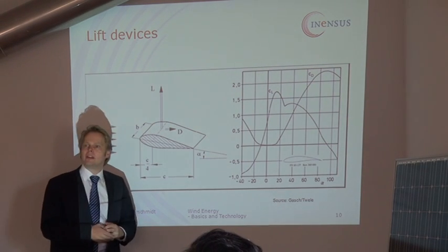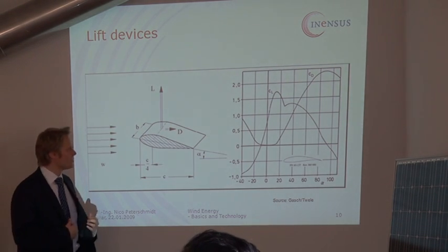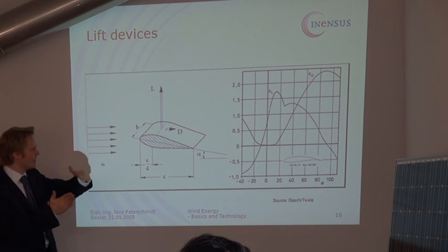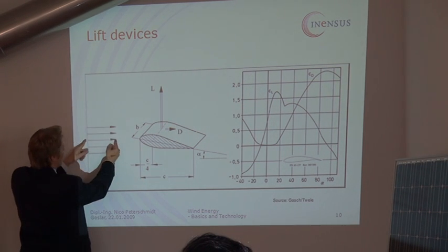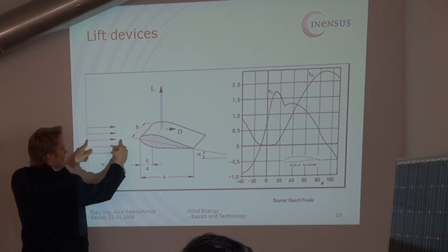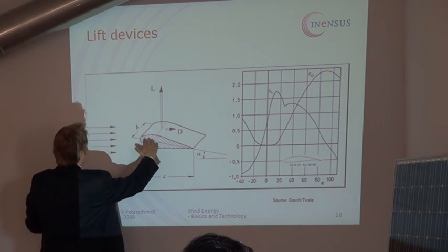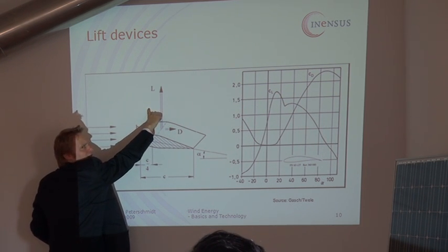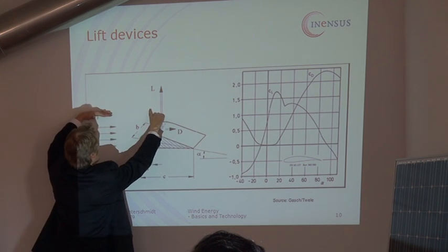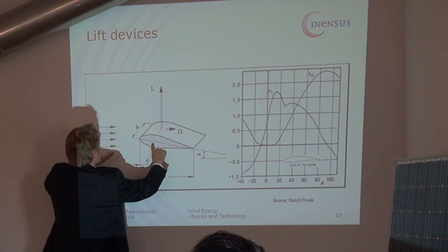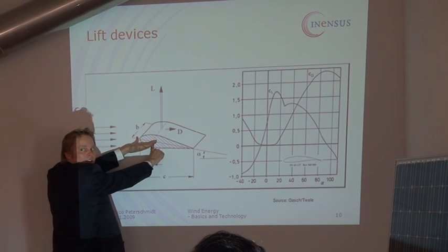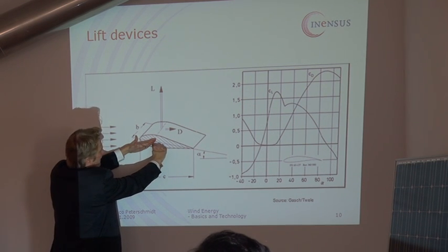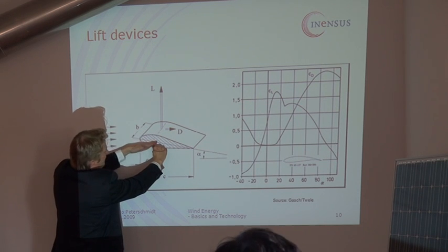You could also design a wind turbine with passive stall. Passive stall means that, as I already said, if you add up the vectors, you've got a vector of this length, for example, for the wind speed. You've got a vector of that length for the rotational speed. Now if you decrease the angle, the angle of attack would then be like this, if you add up the vectors. Now if you decrease the rotational speed, you can decrease this vector, and then you increase the angle.